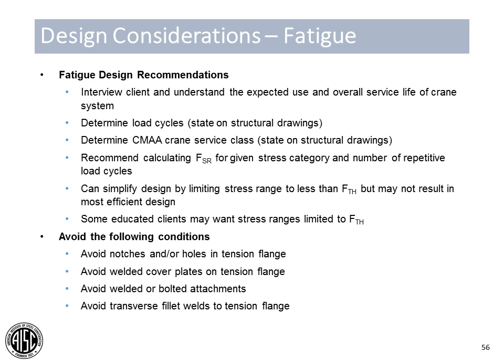Some items to specifically avoid would be notching or putting any holes in the tension flange. Don't weld anything to the tension flange, especially cover plates or transverse welds across the tension flange. And try to avoid welded or bolted attachments. It's always good practice to try to clamp these systems whenever possible to minimize stress risers.